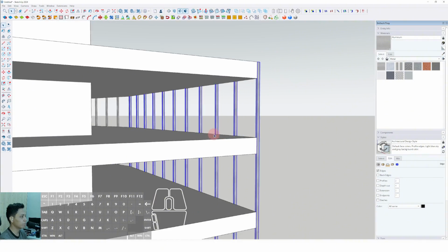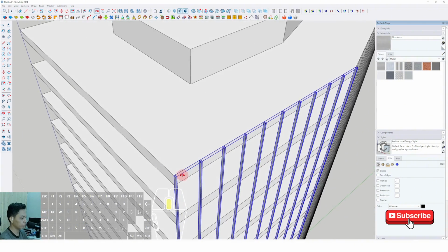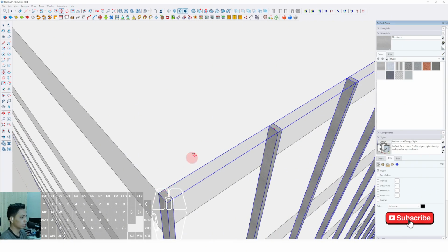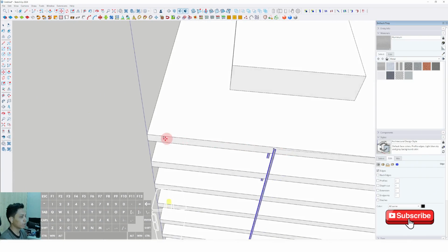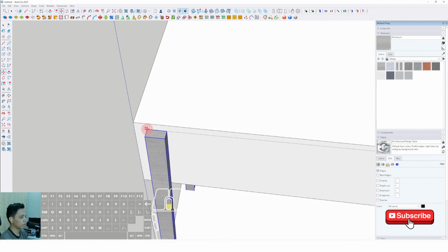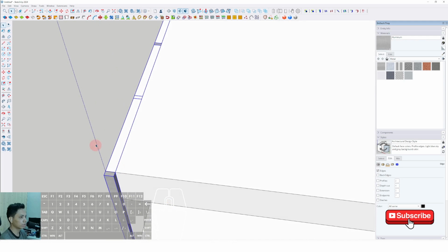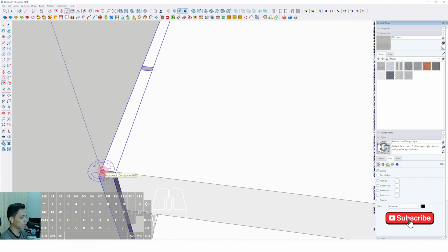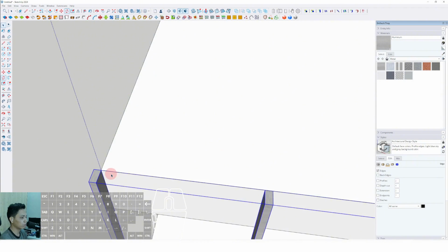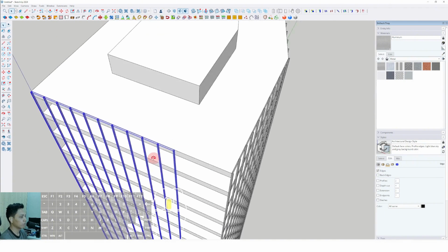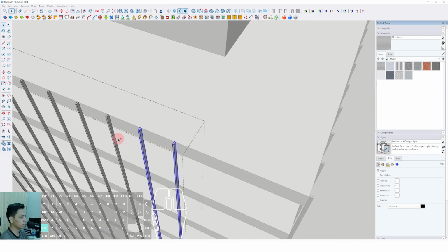Right click and make group, and we will continue to select move, click from this corner, press Ctrl, click this corner again, click to this destination. Okay, this is about the destination. Then just rotate it from this corner and adjust for the building orientation.